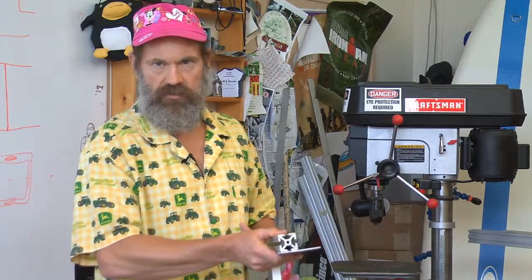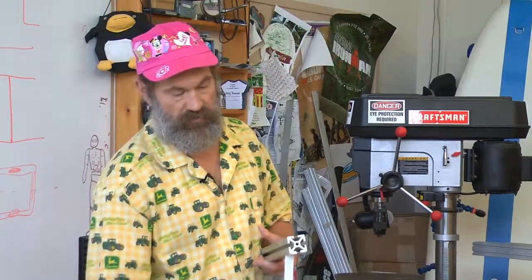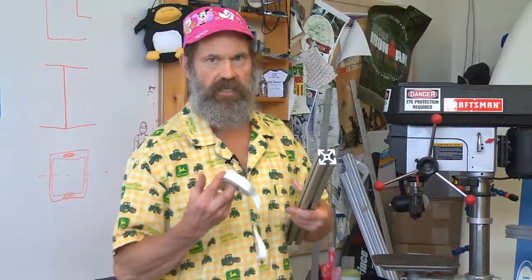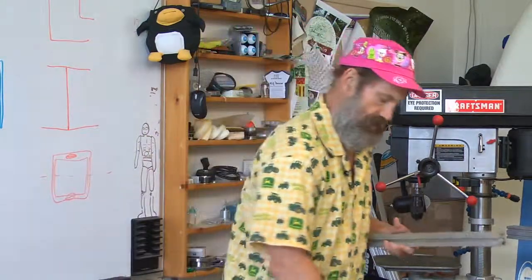So that's a really good structural trick to remember if you're designing machines whose frames are built up with this modular aluminum. But be careful, because if you overload the tape, the joint will fall off. So you have to calculate the shear stress that joint will see, and also be very careful of the temperature that your machine does.